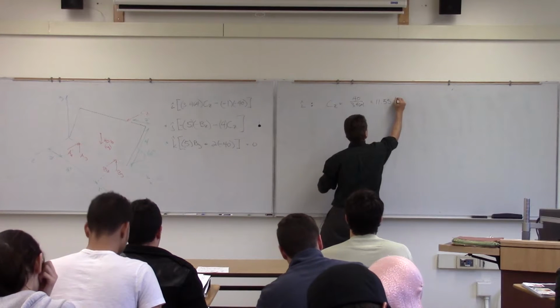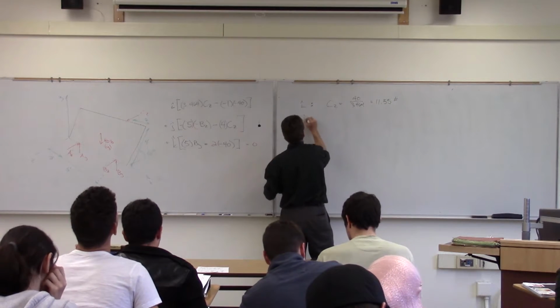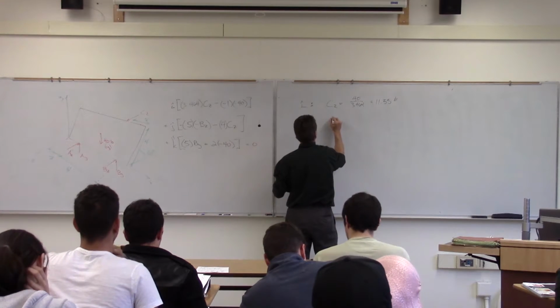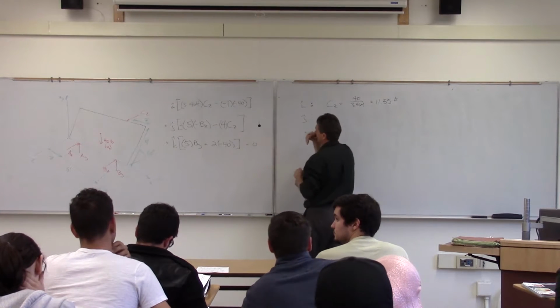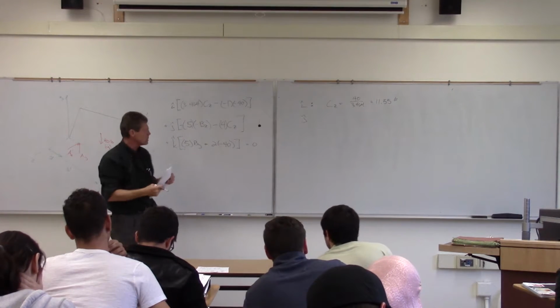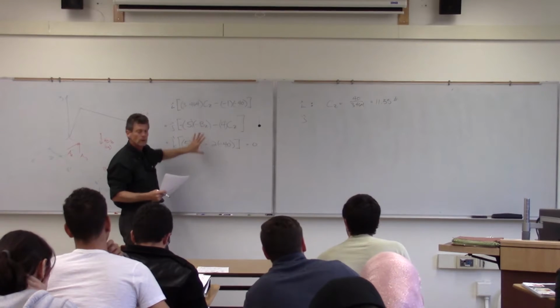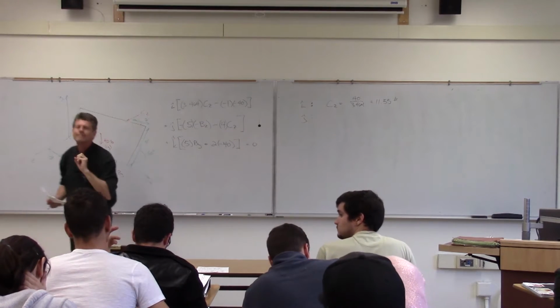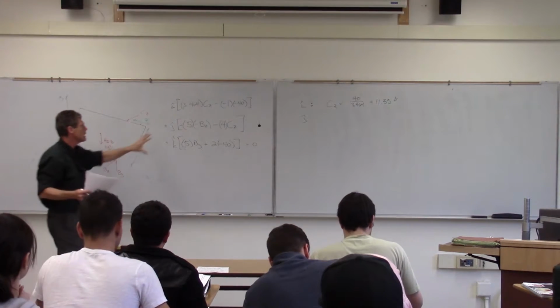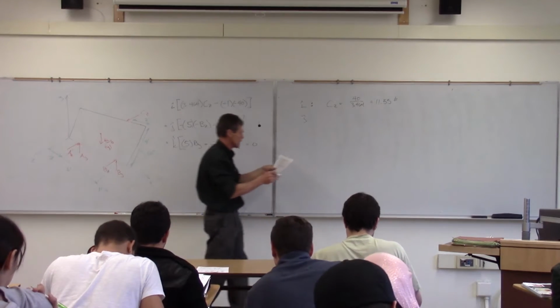11.55. That's pounds, right? Okay, and then we're going to plug that into J. So you're just doing the sum of the forces in each direction basically right now? What I'm going to do is, to drive any sort of vector equal to 0, each of these, this is the x components, this is the y components. Each one equal to 0. And then solve for that. Exactly. That's my 3 scalar equations now. My first 3 scalar equations there.